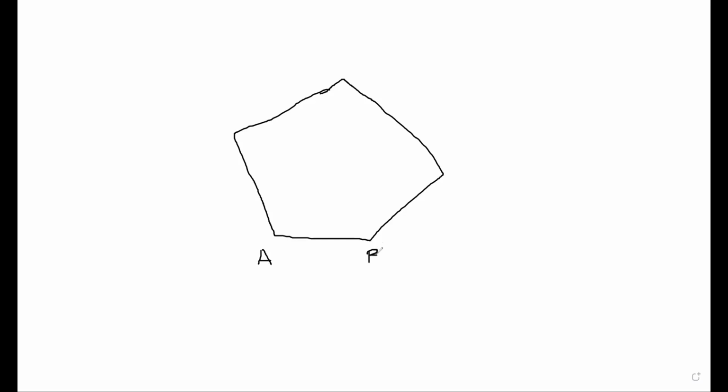It is very easy if we mark at the beginning. So when you do your traverse survey, please mark them in anti-clockwise direction. Anti-clockwise direction means we mark our notations in this way. It is very simple then when you go for completing the traverse sheet.